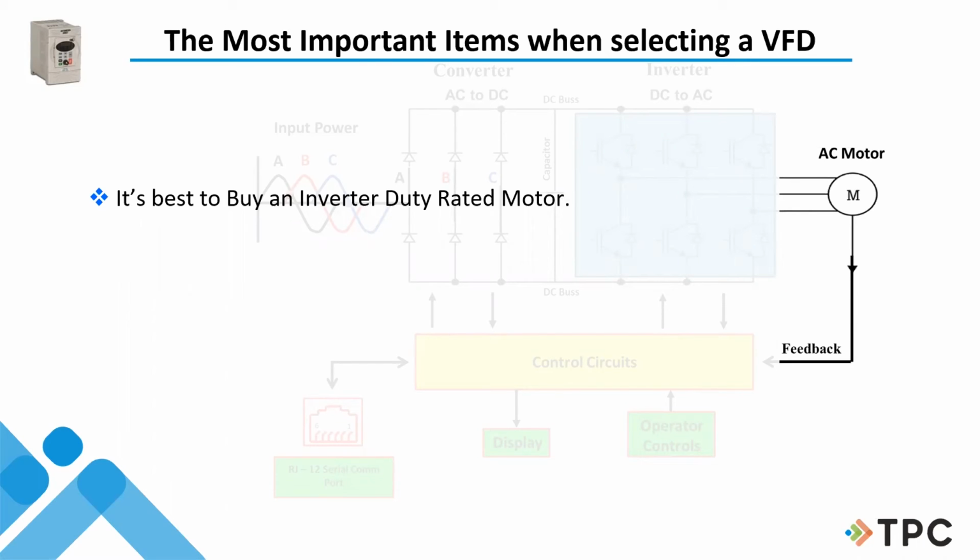that they can't vibrate. Remember, we said that when we take this drive and we send that frequency out to that motor, it's a choppy looking thing. It's not a nice little curve as we normally think of a 60 cycle waveform. And so it creates a lot of forces in there, and we need to make sure that that motor has the right amount of varnish and right amount of tie down so that the winding doesn't vibrate, because if one copper wire gets loose and starts to vibrate, before you know it, it's going to short out and your motor's going to burn up.